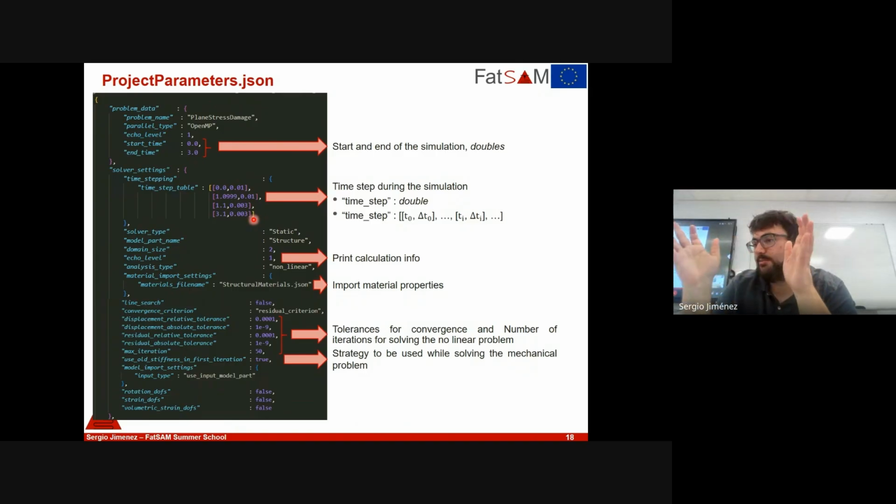Okay, now I know the time step. I perform my simulation, I update the strains, then I compute and do the calculation of the stresses. Now everything is solved, and I ask Kratos, okay, which is the new time step to be applied? And it will ask you, which is the current time? So it will go here in the table and it says, okay, my time is 1.0987, which is still below. Yeah, so it will check that.